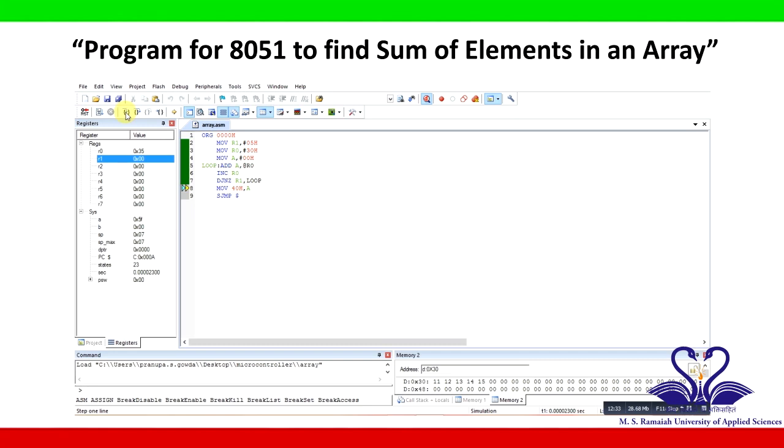Once this is done, now R1 is equal to 0, that is, here we are taking DJNZ R1, loop. So once it keeps on decrementing, initially it was 5, then it became 4, 3, 2, 1. Now it is 0. Once R1 is 0, the condition is false, it will come out of the loop. Once it comes out of the loop, the result was in accumulator, that is, the sum of the elements was stored in accumulator. That sum will be stored into 40H memory location as a final step.